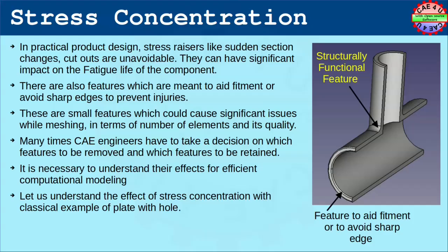In the picture we could see that there could be a fillet, which contributes to the stress redistribution and hence reducing the stress concentration. Whereas a chamfer at the end of the pipe might be helpful in terms of fitment or to avoid sharp edge preventing injuries during handling.